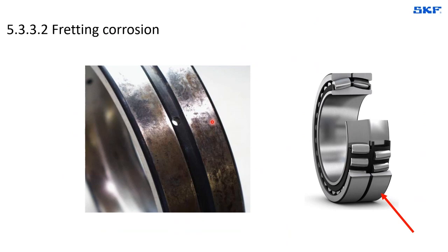We do not mean here that mounting a bearing with a loose fit is wrong. No, that's required in many cases because of mounting and dismounting conditions and because of the locating, non-locating behavior we want to get in a bearing application.